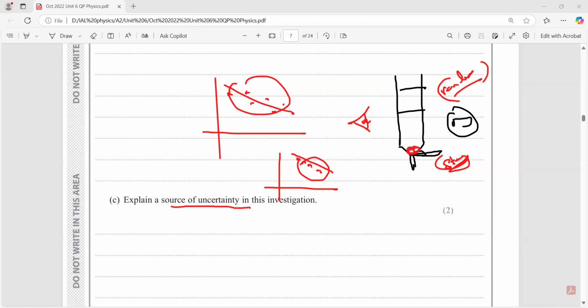This is a systematic error, but if you are refilling every time, the amount of the air trapped may change. And in that case, this error will become a random error. Look, when I fill one time, let's say we were doing this experiment and we only fill the burette or the funnel once, only one time the liquid will come out. But if I have to refill this, maybe sometimes the amount of air added will be more, sometimes the amount of air added will be less. So the value variation will be there.